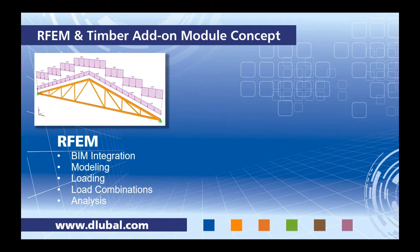So to explain RFEM and the timber add-on module concept, for those of you who are not familiar with our software, the main program is RFEM. This is where we can integrate with BIM software such as Tekla, Revit, AutoCAD. We'll be doing a majority of our modeling in RFEM. You'll also be loading the structure and creating your load combinations, whether that's manual load combinations or according to our load combination generator per the ASCE 7 or the NBCC code. And lastly, we'll run a full analysis in RFEM. So things like internal forces, deflections, stresses, this can all be done in RFEM alone.